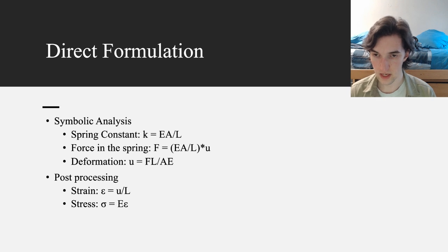This equation can be used for any other elements that we decide to add, and it is a decent approximation of the stress and strain and deformation in the deflector. There are some improvements that can be made. As mentioned earlier, the load was greatly simplified for analysis. A better model would consider the bending stress.